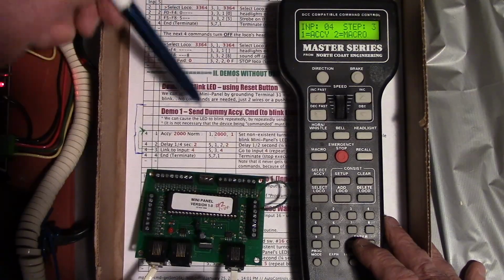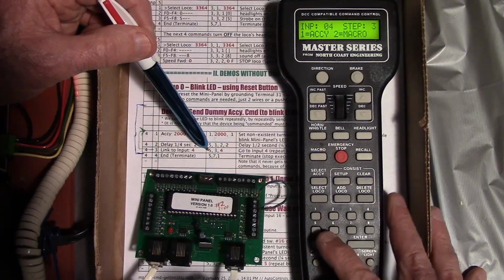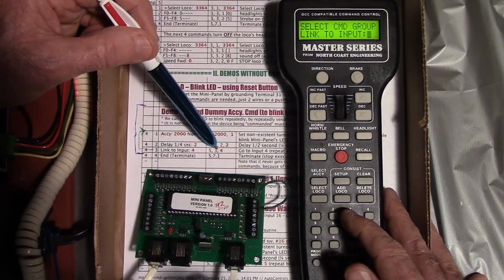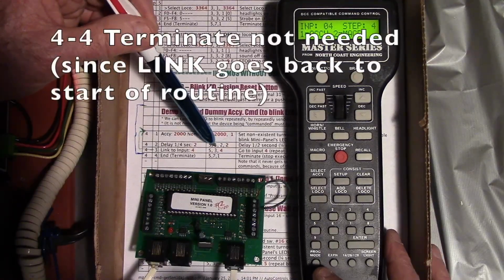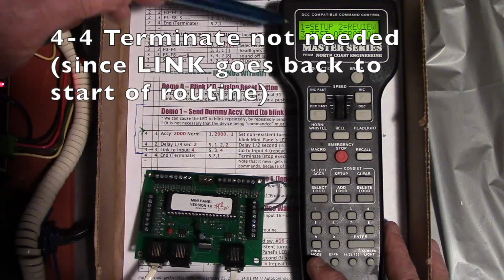Now input 4, step 3. That's going to be the link command. So we're going to push a 5 for other, then a 3 for link. Link to input what? We're going to tell it 4. Enter. So we're done entering commands. We'll push the program escape button down here to back out to our main menu.